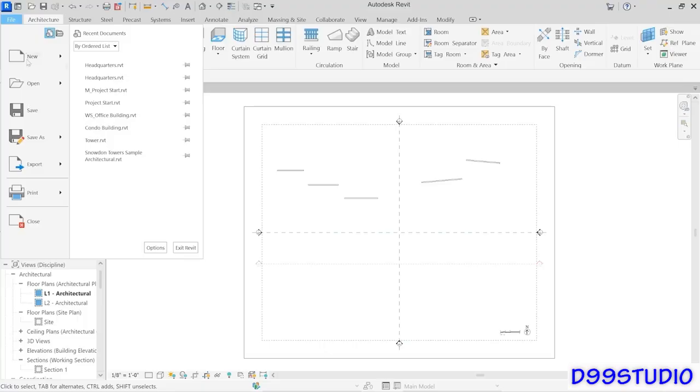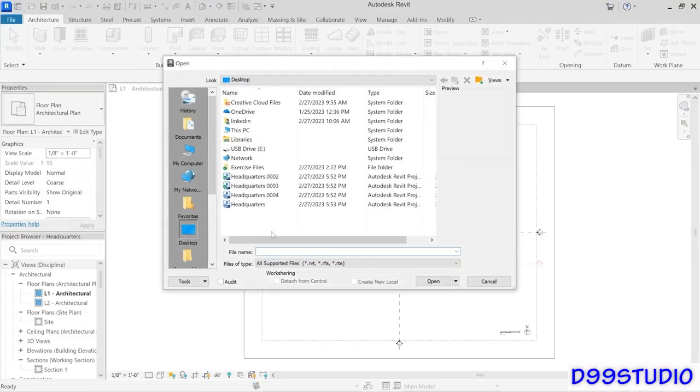And now I'm going to go to File and choose Open. And now notice what happened. Backup 1 is no longer there. That's because we set our quantity to 3. So what 3 means is we're going to get up to 3 backups, but no more than that. And so it will always throw away the oldest version, number 1 in this case, and I'm left with 2, 3, and 4. And of course, the headquarters file represents the current state of the project.